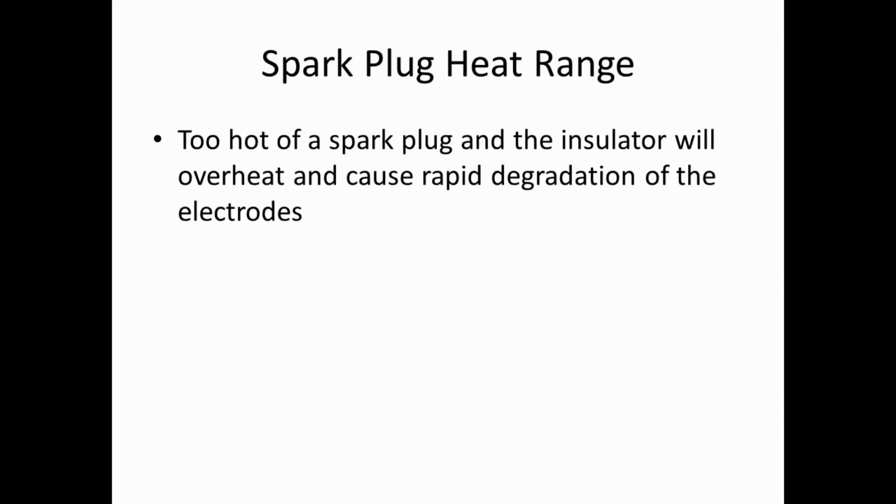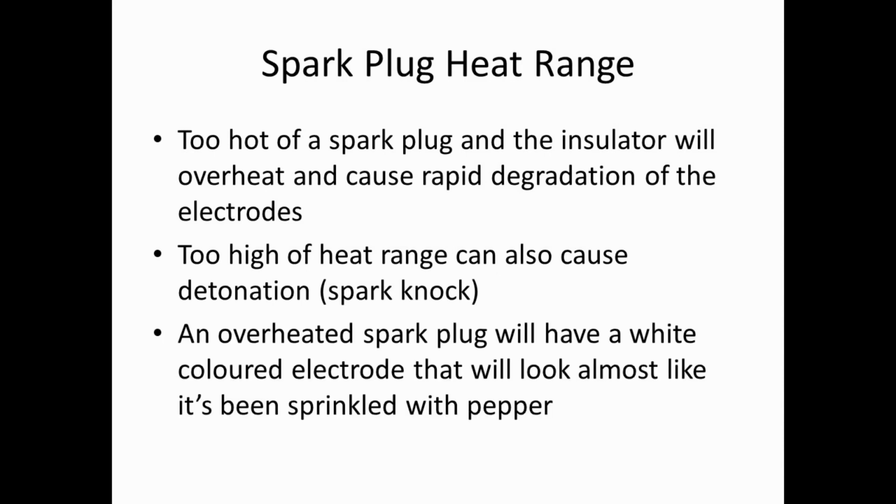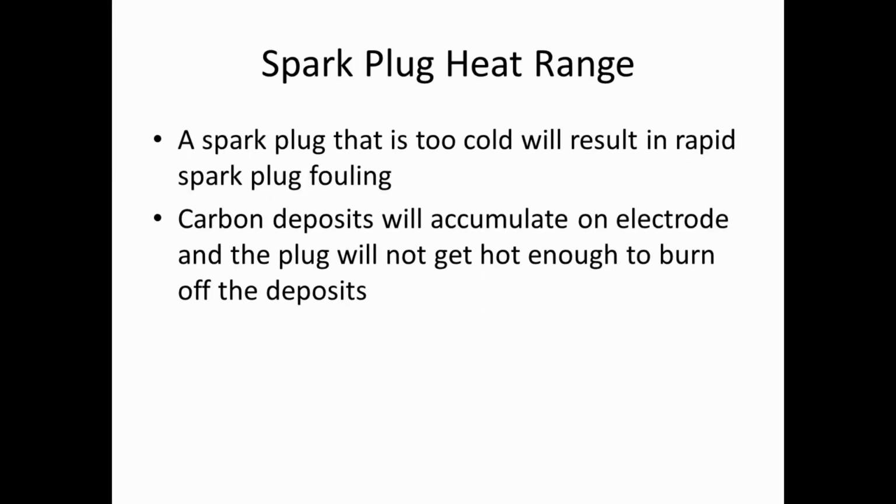If you have too hot of a spark plug, the insulator will overheat and degrade very quickly. It can actually cause detonation or spark knock, which is a totally different lecture altogether. Because that insulator tip is glowing really hot, it serves almost as a glow plug. So when the fuel comes in on the intake stroke, it can actually ignite it if it's glowing hot enough. An overheated spark plug will have a white colored electrode. It almost looks like it's sprinkled with pepper a little bit.